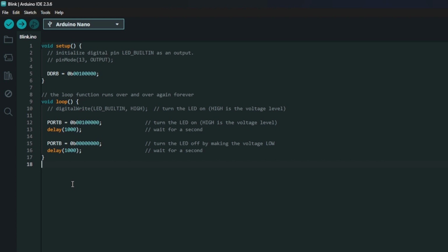This sounds very complicated, and if you don't know C and pointers in C, this will be a bit complicated, but essentially what it does is it creates kind of like a variable, which is a pointer, that will point to a memory location, like an actual physical memory location block inside our microcontroller. This memory block they called port B.